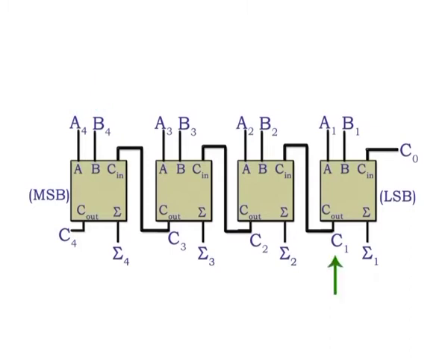The carry output of each adder is connected to the carry input of the next higher order adders as indicated. These are called internal carries. In keeping with most manufacturers' data sheets, the input labeled C is the input carry to the least significant bit adder.